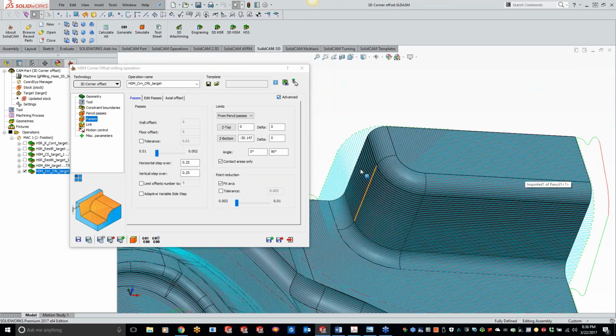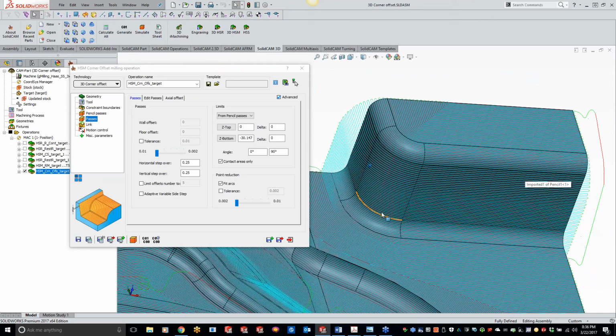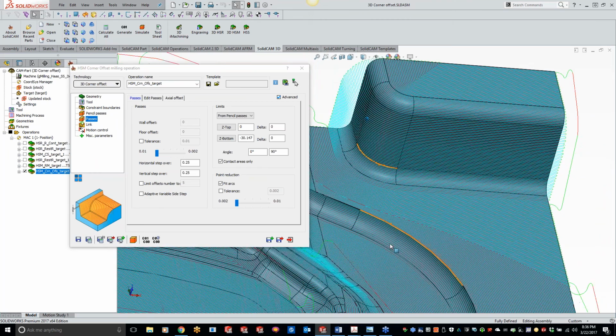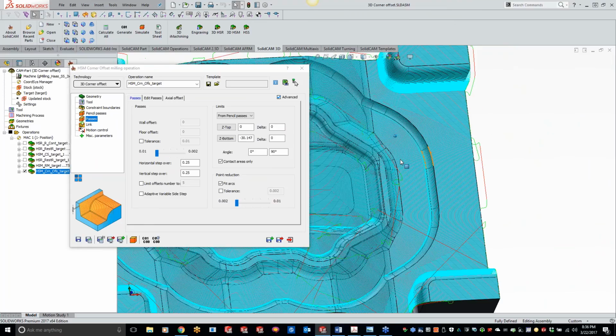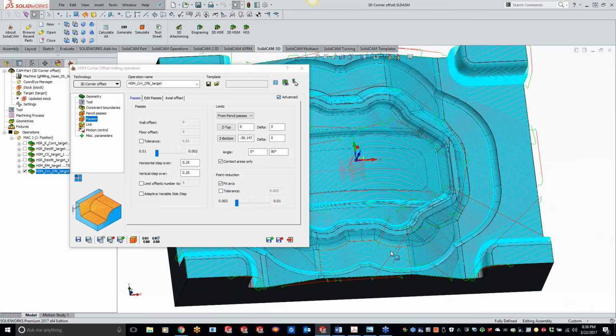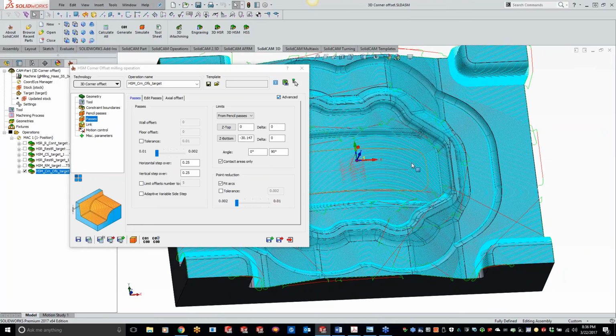You'll see that the toolpath is following the contour of that surface, coming in here, following the inner, going from straight lines over here to turning into more of a circular toolpath, following all the way around, and then getting into the flat area, basically doing a hatch style toolpath for you guys, but also doing that 3D constant step over too, so it's constantly stepping over that same amount. So real nice toolpath, following that contour geometry there.